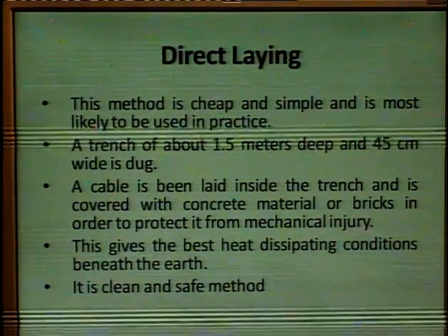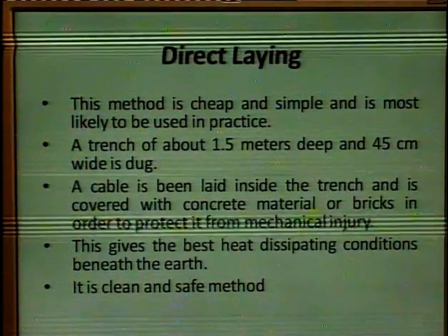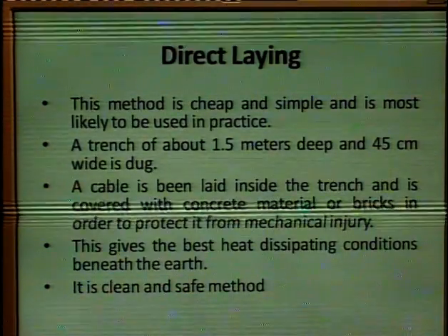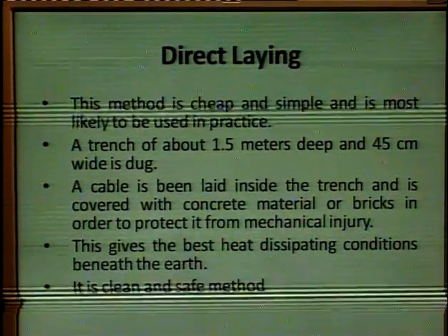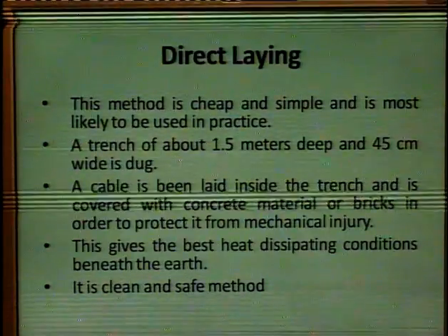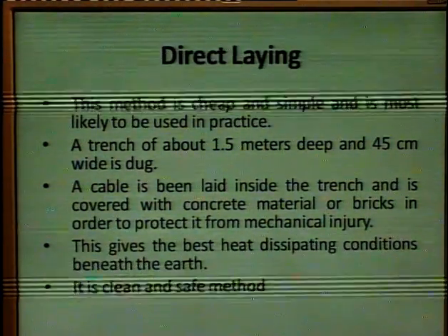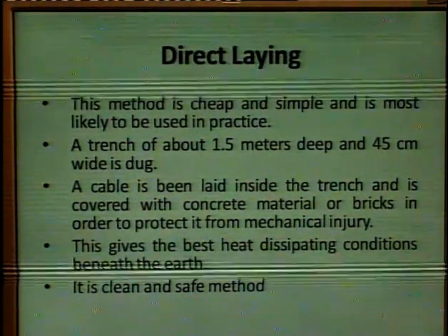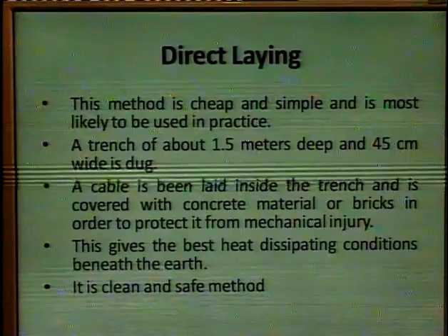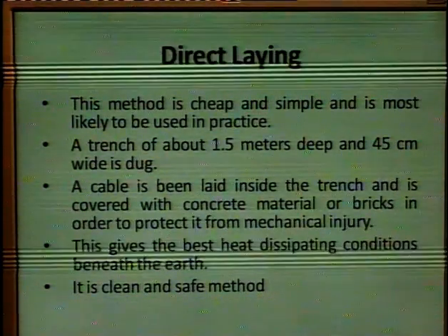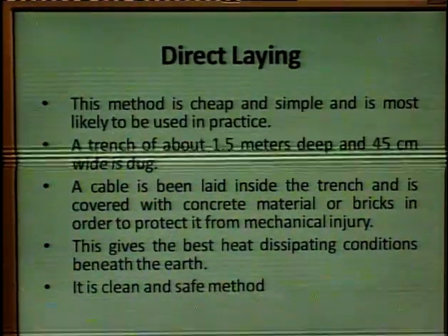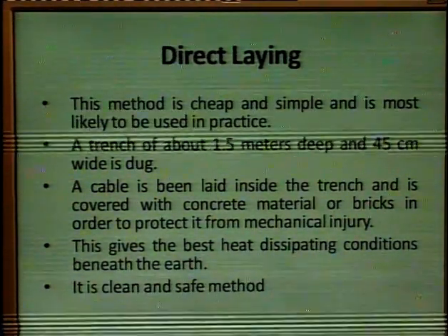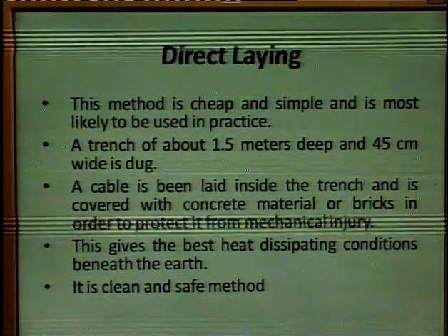First is the direct laying method. This is a very cheap, simple, and the most likely to be used in practice method. This is the most simple: just dig a trench, lay the cable, and cover with concrete or with the soil.